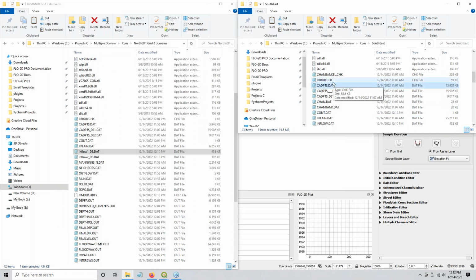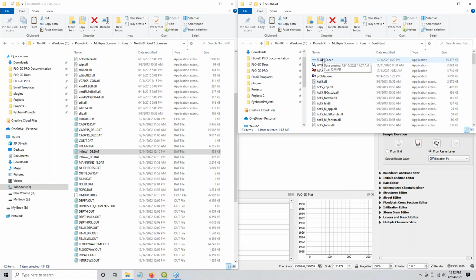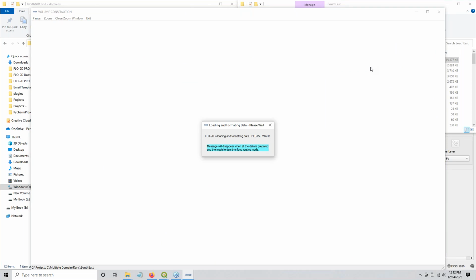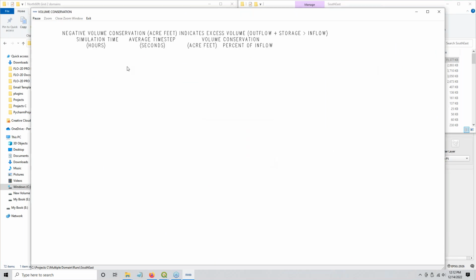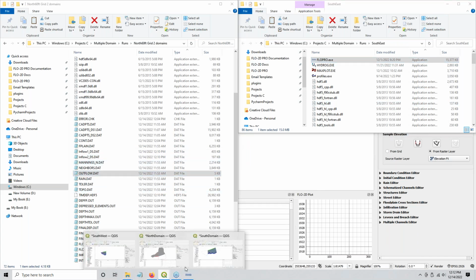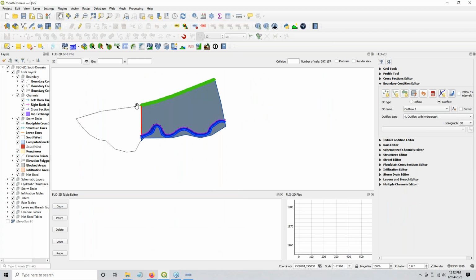And then this one is ready to run so that we're getting the inflow from the north and from the southeast. So I'm going to let this one run. What this is giving us now is, I'm going to show you right here. This is taking the rain on grid, the inflow across the boundary, computing the flow across into the downstream boundary to get the inflow node for the downstream boundary. So then these inflow nodes will just have to add to the other ones. So that's why this is overly complicated.